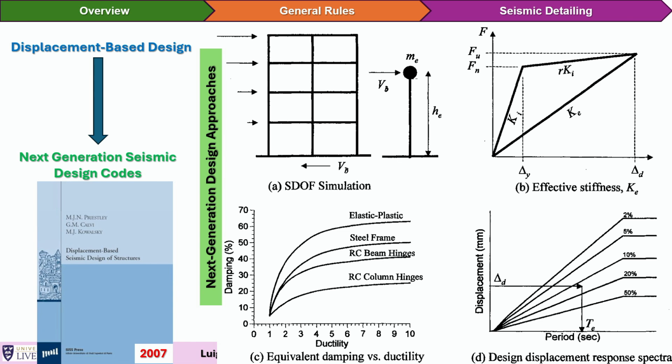So what you do, and this has been done in the literature, we have a relationship between ductility, high damage, with something that is still a sort of invention, but is a way of tackling nonlinearities, high damping. And then we have curves that correlate ductility levels with damping level.